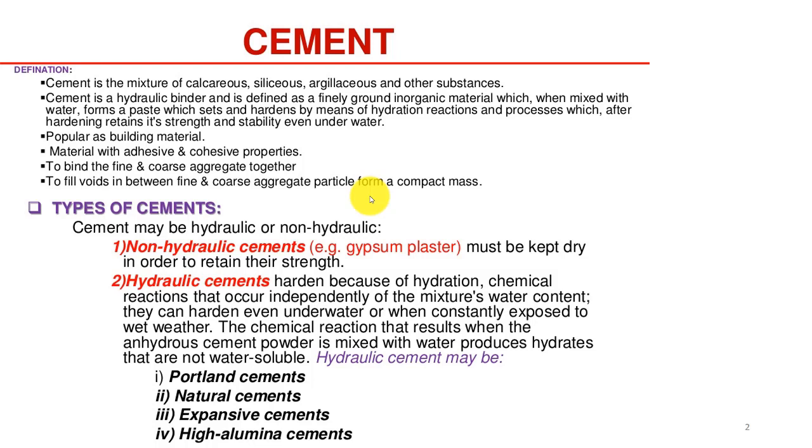After the clinker production, you allow the clinker to cool down sufficiently, and then grinding of the clinker takes place with some addition of gypsum, depending upon the requirement of how much open time you want to give the cement. So basically, these are the constituents: calcareous and argillaceous rocks can be used as a prime source of raw materials.